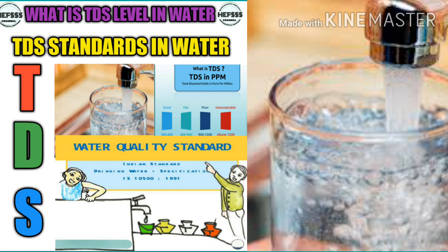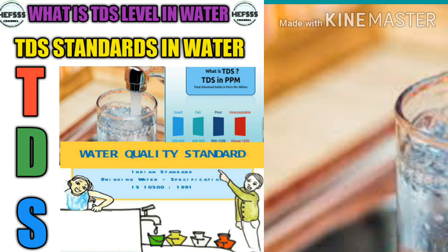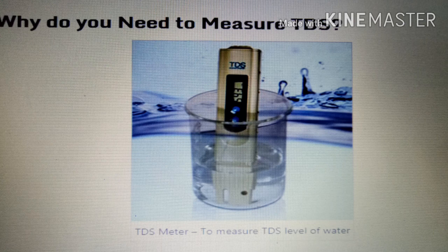So, which water purifier is the best? One of the most important things to consider when looking for a water purifier is the TDS level. Depending on the TDS level, you need to decide whether you need an RO, ultraviolet, UF or UV water purifier. Hence, it is important to understand which water purifier is ideal for the TDS level. For a TDS of 0 to 200, a UV water purifier; 200 to 300, an RO plus UV water purifier; and 300 to 500, RO plus UV plus UF.